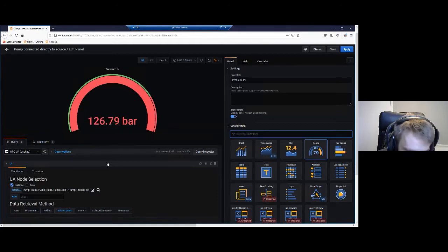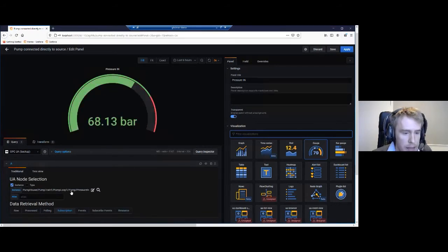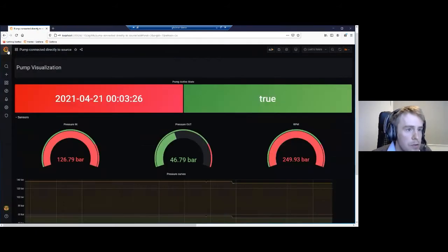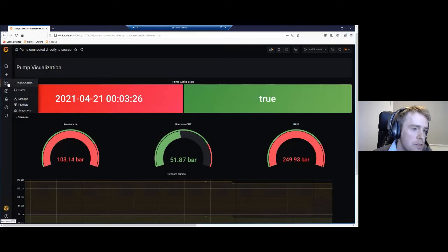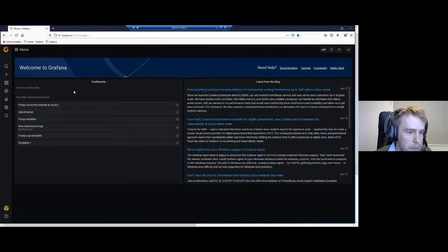And we see here that we've connected this to an instance in the UA model. So this is connecting to the pump house, pump train 1, pump loop 1, and then the pump, and this is connected to the inbound pressure. So this is, of course, still locked to defining one dashboard for each node in the information model graph, if you will. So what we've been able to do is to implement this port adapter pattern.